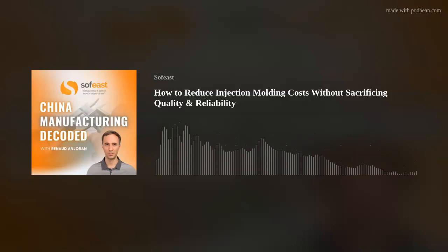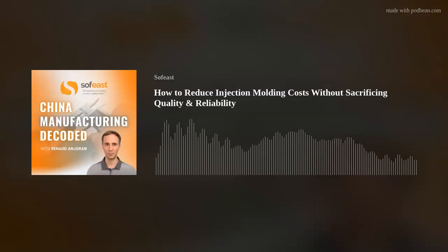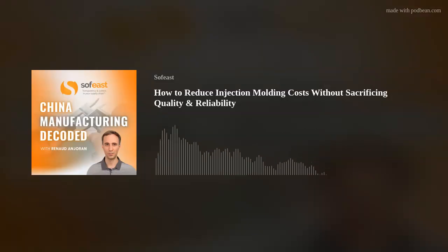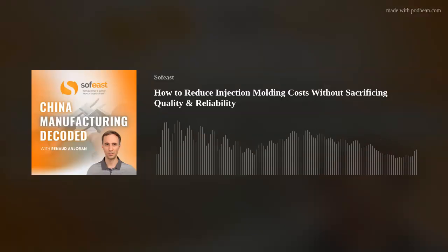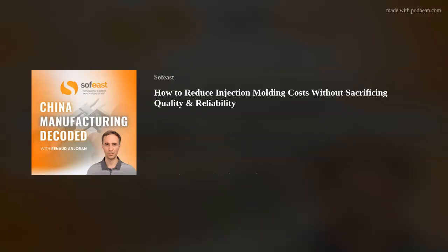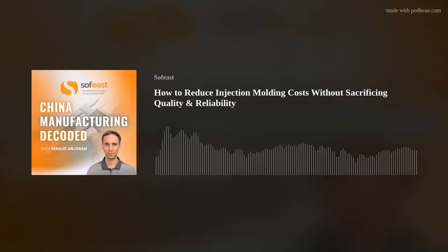However, the amount of labor that goes into producing a mirror finish, and the slightest imperfection or slight bit of dust, slight imperfection in that surface will show up like a sore thumb. It's definitely not the way to go forward unless you really, really must have it. Okay? So avoid mirror finishes if possible. Okay, what's another one?